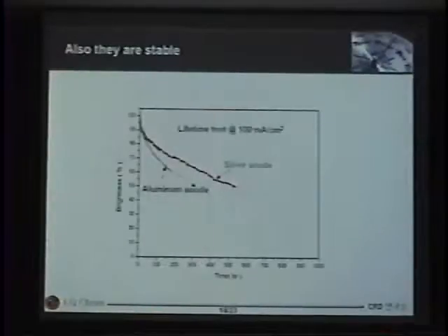Next. And this is a device lifetime. And this is a very practical device. It's not only showing the very peculiar anode structures, but it gave very good lifetime. At this time, we got about 300 hours of device life. Our best optimized devices with nitrogen plasma ITO was about 800 to 900 hours, but at the time we got 300 hours, and with silver we got over 500 hours.